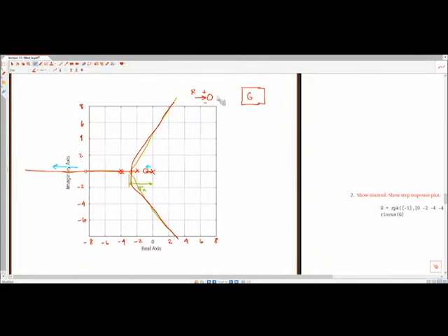I'll put a gain k out front here because this is going to be in the form of what we're talking about. But a gain does not add poles or zeros, it's just a gain, right? It does not change the solutions of the numerator denominator. Right? And so if we talk about open loop, that would be just this system here, no feedback, right? And so we can figure out what the poles and zeros here are just by looking at the numerator, denominator, setting them equal to 0, understanding what the values of s are such that that's true, right?